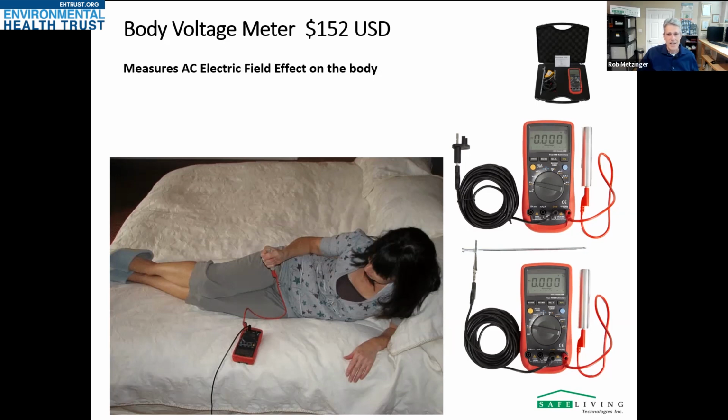You have to connect one end to ground, and in this case, it just has a receptacle outlet adapter that you can plug into a receptacle to get ground, and that's where the black lead goes, into the common port on this voltmeter or multimeter. And then we have our hand probe that the person holds on to, which goes in the positive socket here, the red cable, when we're measuring AC volts.